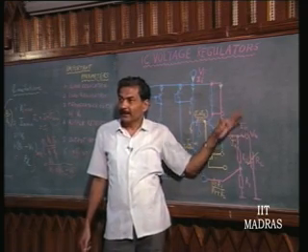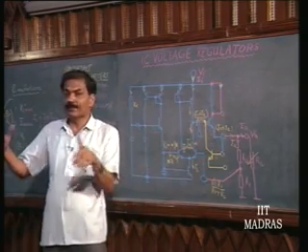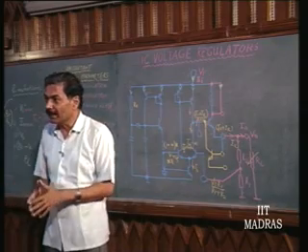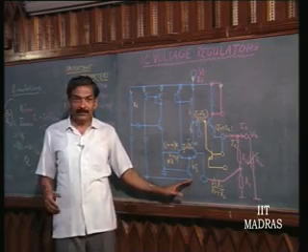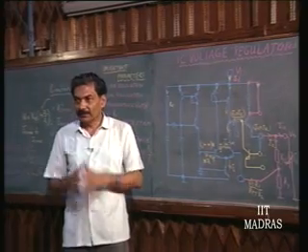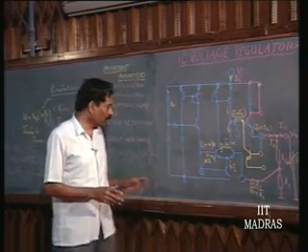That is why I am saying as far as this transistor is concerned, it is only the Vi minus V naught differential that matters. That will always be less than Vi, whereas other transistors are there wherein collector base potential can be higher and they might break down.